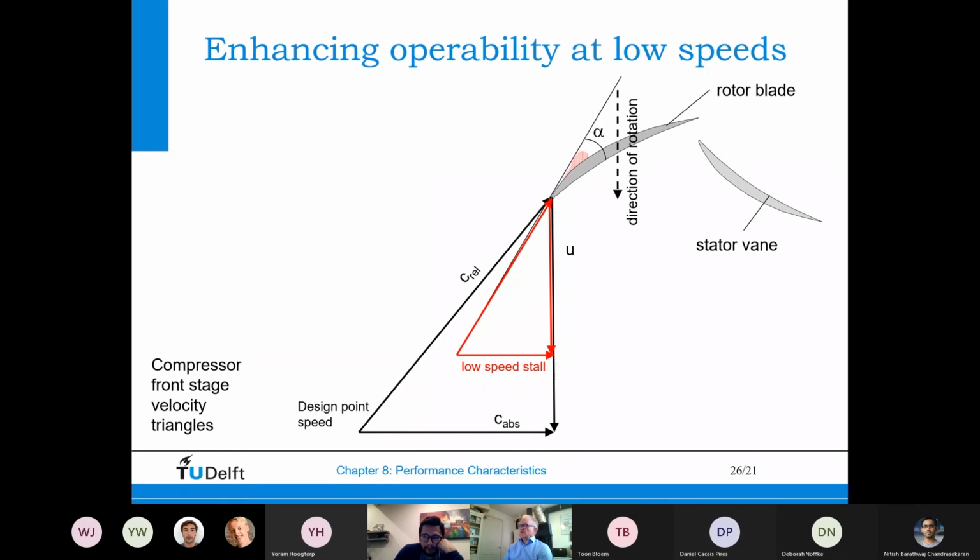And very often, a lot of system simulation puzzles are focused around this problem, because there's various ways you can actually change this. You can change the stator vanes or inlet guide vanes, or you can actually control this factor if you like. But then you have the variable geometry case. Now we're going to that solution now.